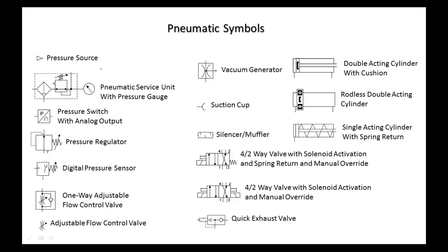Hydraulics, though, you can control the flow down to whatever you want, as long as it's below the range of the flow of the pump. The pump's running at the same speed, so it's going to give you the same flow. Most of our continuous duty compressors give you a pretty constant flow, but they're very, very expensive.